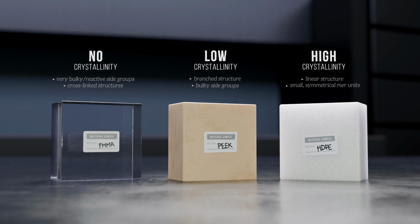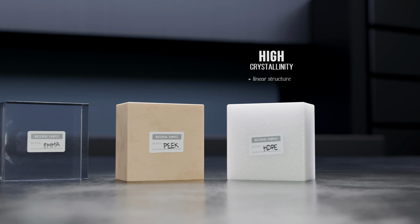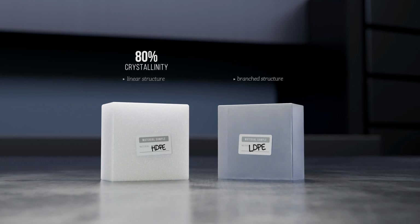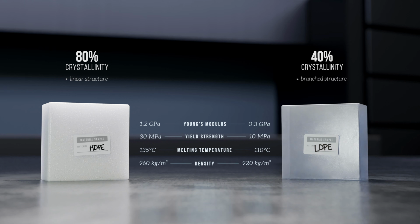High-density polyethylene has linear chains with minimal branching, with crystallinity of around 80%, whereas low-density polyethylene has a branched structure resulting in much lower crystallinity of around 40%. The difference in crystallinity explains why the two materials have significant differences in stiffness, strength, melting temperature, and density, despite being made from the same repeating mer unit.